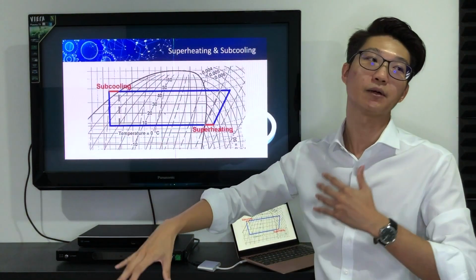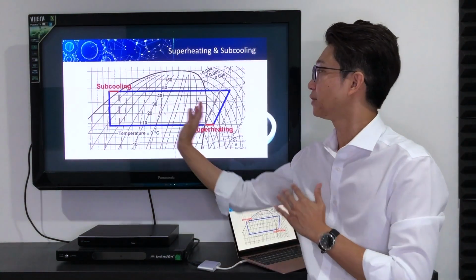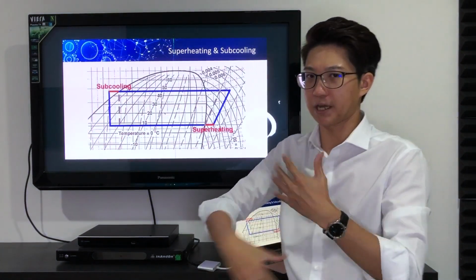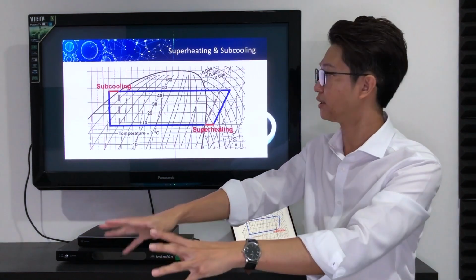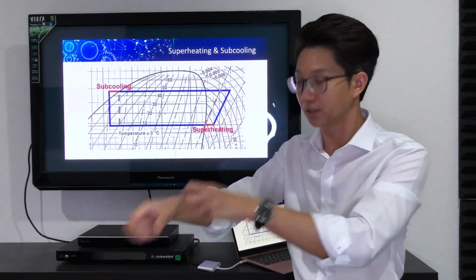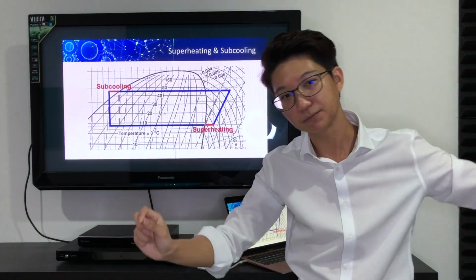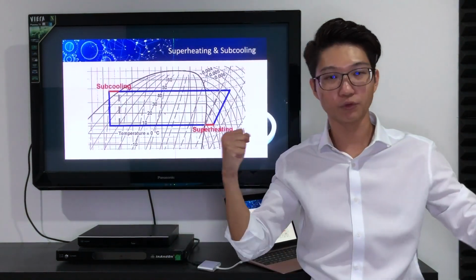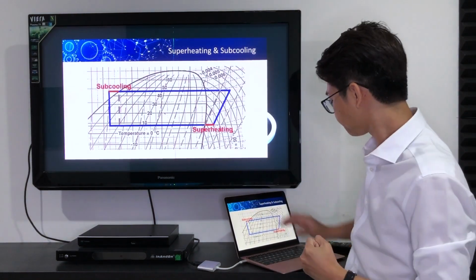Maybe one of the ways is we slightly oversize the condenser outside. We subcool it, like we encourage the refrigerant to keep on rejecting, reject more. It's okay to drop some temperature, reject more. So subcool. The refrigerant comes back, we know it is fully ready, 100% capacity, ready to absorb heat, right?